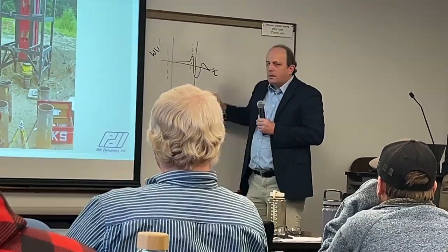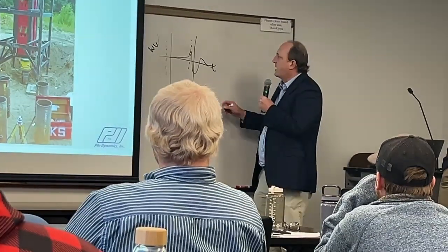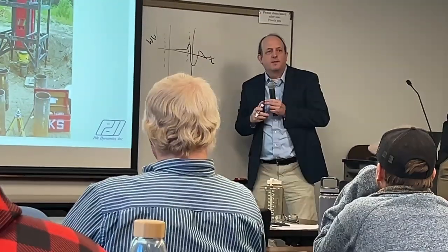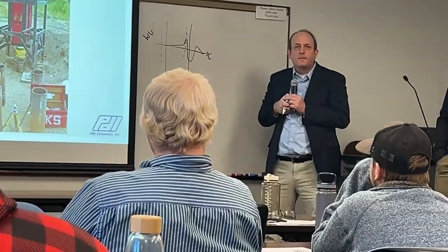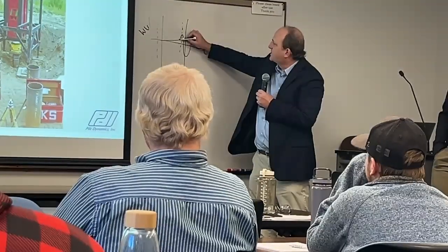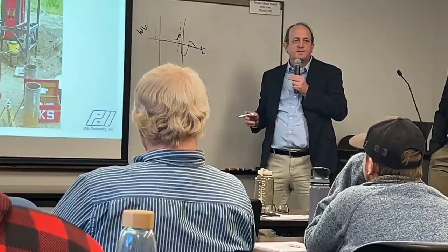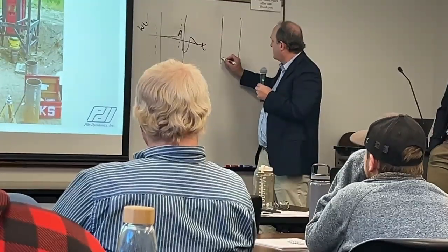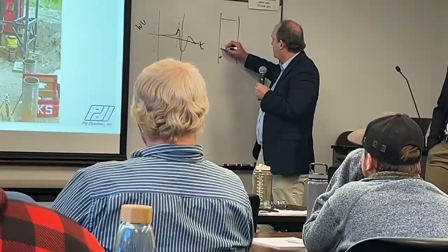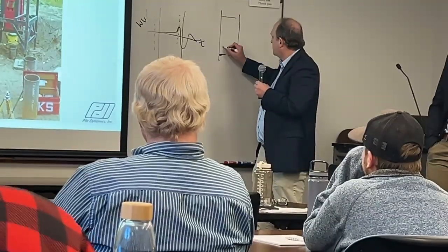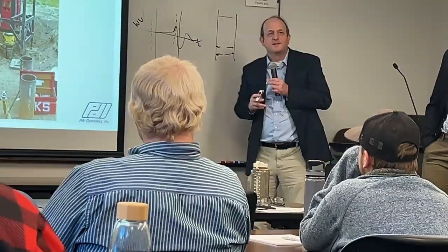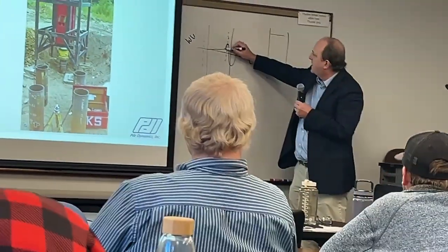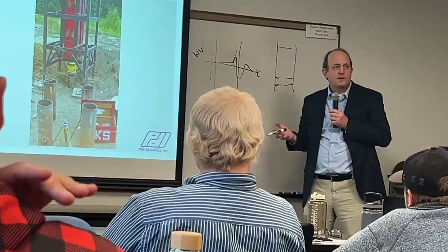So what we sometimes see with open piles is an abrupt increase at the base where the plug is developing. And so this looks like resistance, and it partly is resistance, but it's also soil towards the bottom that's really pushing against the side. And so we don't tend to see these types of sharp increases in closed-end pipes.